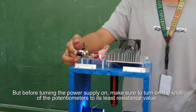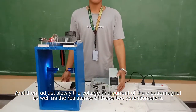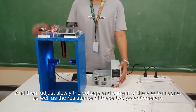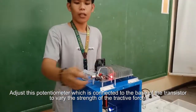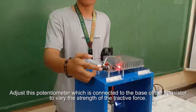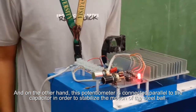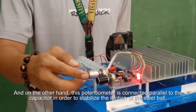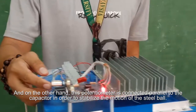its least resistance value, and then adjust slowly the voltage and current of the electromagnet as well as the resistance of these two potentiometers. Adjust this potentiometer, which is connected to the base of the transistor, to vary the strength of the attractive force. And then on the other hand, this potentiometer is connected parallel to the capacitor in order to stabilize the motion of the steel ball.